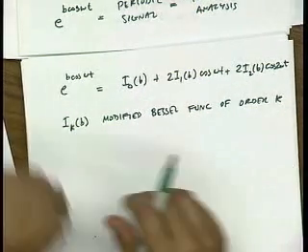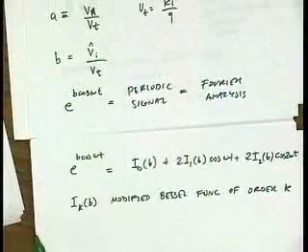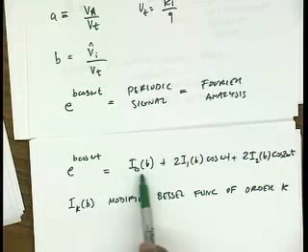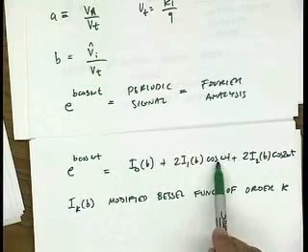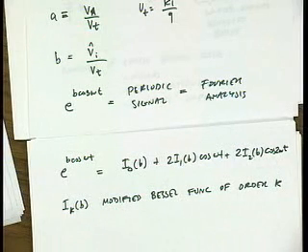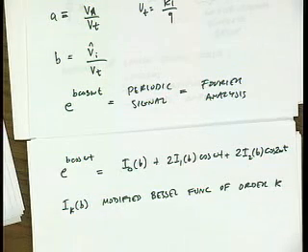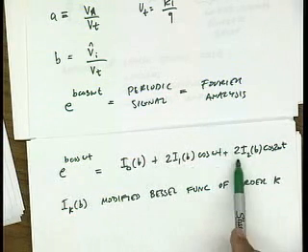Okay. So no magic here. All I've done is said, what's the Fourier series for this? So the Fourier series has a DC term, a cosine omega t, a cosine at 2 omega t, and so on. Because of the even symmetry here, it's a cosine series. There's no sine terms. And the coefficients are just these modified Bessel functions.